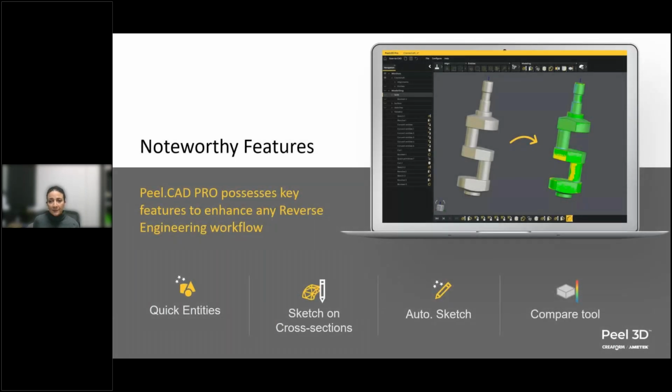So Peel.CAD Pro is packed with key features designed to enhance and streamline any reverse engineering workflow. So here are a few highlights, which I'll show in a CAD creation project in the next few slides. Quick entities. This feature will allow you to create multiple entities quickly and efficiently. It's perfect for speeding up the alignment and segmenting your mesh with ease. Sketch on cross sections. With this feature, you can work seamlessly with the cross sections to precisely extract various entities directly on the scan data with simplicity. Auto Sketch. Auto Sketch automatically creates lines and arcs, saving time and delivering faster results. And you set the allowable deviation between the sketch and the cross section yourself.